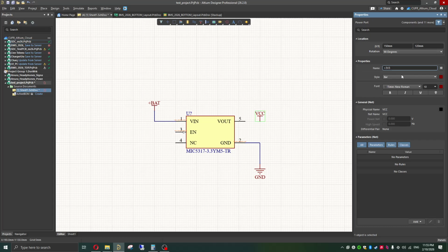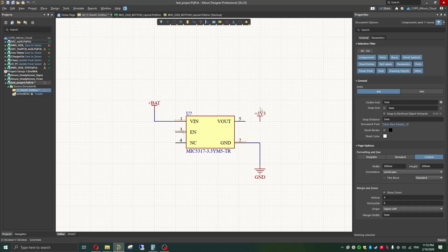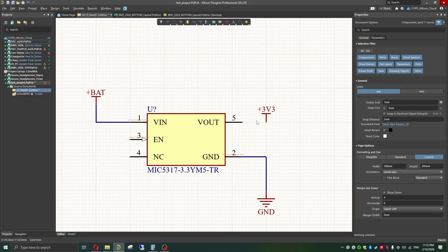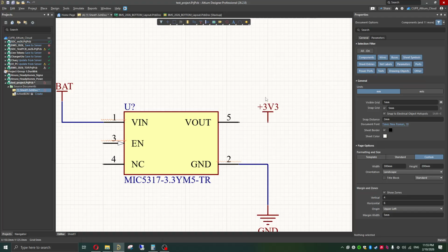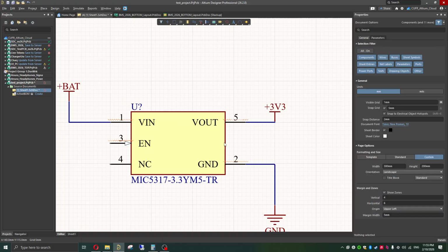If you're not familiar with that convention, this is pretty standard when you're looking at schematics and defining rail voltages, because a decimal point on a schematic from far away just looks kind of confusing. It's best to just indicate voltages like 3.3 or 5.5 as 3v3 or 5v5. Alright, so now pressing Control W again, I'm going to connect V out, and now I've defined that power port.